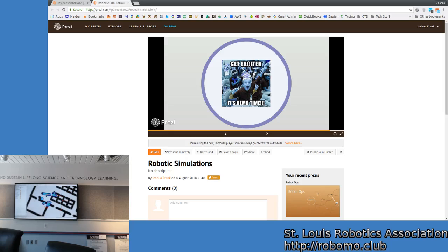We have the local cost map. The local cost map is not a real thing, it's a calculated value. There's a part of the navigation program that reads in the laser scan and finds nearby obstacles. That's what these are right here. That's just visual feedback so I can understand what obstacles the robot believes are in front of it. If it's running into a wall and I can see that my local cost map is not seeing that wall, or more likely on my robots, that my laser is too high and it's hitting the table, I can see that the cost map doesn't see the table.